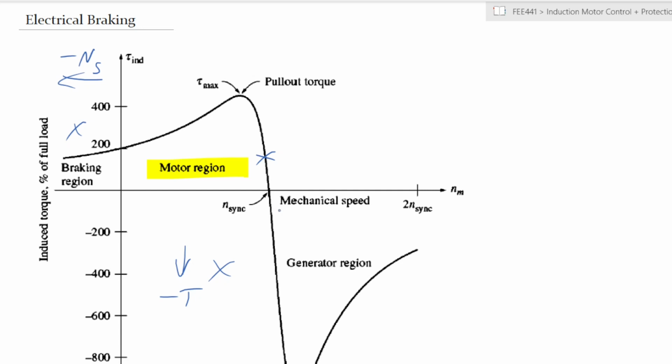Generally, you would use mechanical braking, which is the use of friction, brake pads, slowing down the machine, and you stop applying a voltage at a certain speed, at a certain level, and then you slow it down to a range which is what you need. If you want to get it down to zero, you can use any of the options that you're talking about as an alternative to mechanical braking.